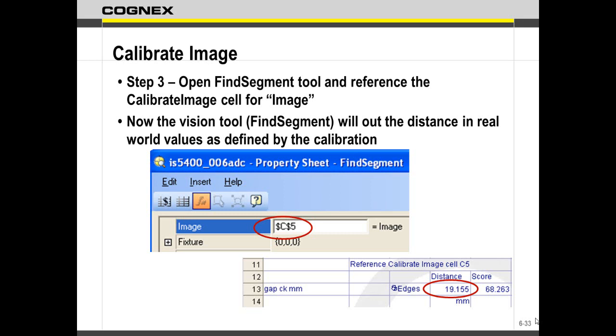What about the blob tools? Well, what's their units right now? Square pixels, because they're an area. We can calibrate that. We'll have them in square units. Beautiful, that's fine, because all we're doing is looking at areas and pushing them out. Histogram, should we calibrate that? Exactly. You are picking up grayscale values. That's not calibrated, so it's not going to do anything for that. It's going to say, whatever, my grayscale is still my grayscale.